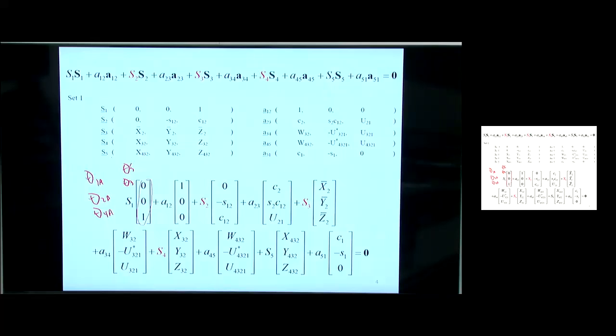So for the A case, I know all the angles. I know all the alphas. This has theta 2 in it, and this is kind of lying to us. It only has theta 2 in it, but theta 2 for the A case, so those are all going to be numbers. Granted there's a lot to expand, but for the A case, I am going to know the directions of all those vectors because I know all the angles. And then what do I have? I have three linear equations and three unknowns.